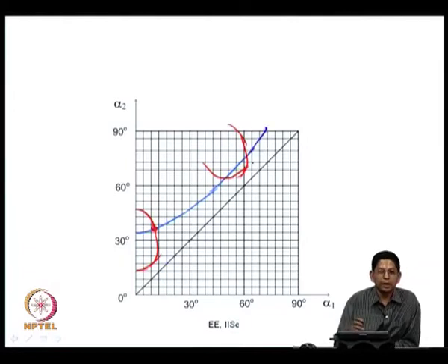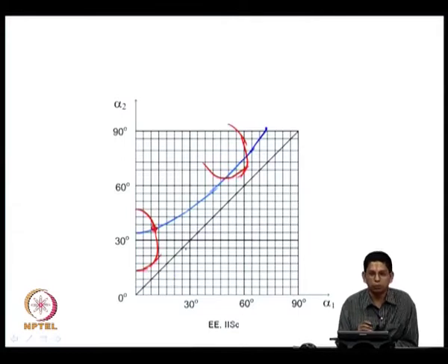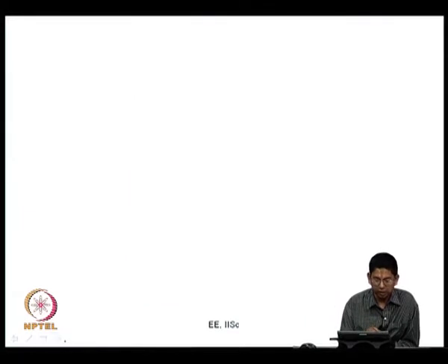So, if you are within the range where 3 solutions are possible, which point you get depends on your initial guess and your iterative procedure. It will take you to one or the other solution. And if you are within the range which is greater than that Vc that I had told before, you may not get any solution at all. So, that is the selective harmonic elimination problem.